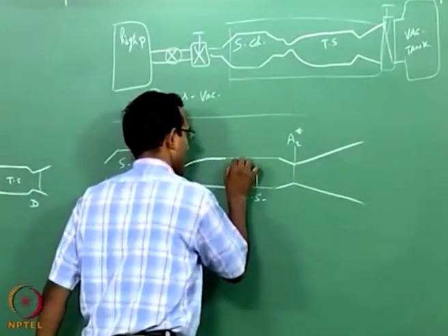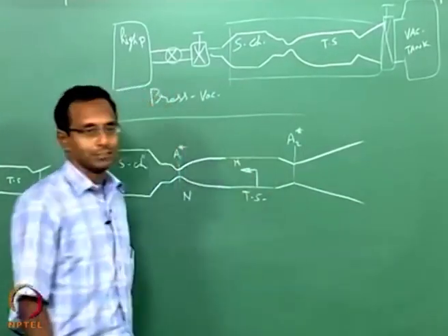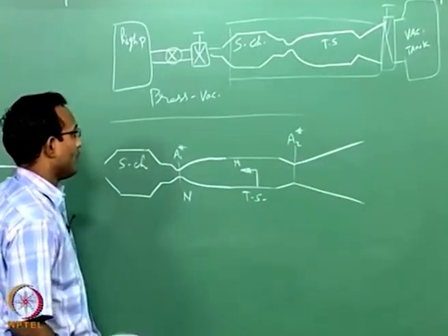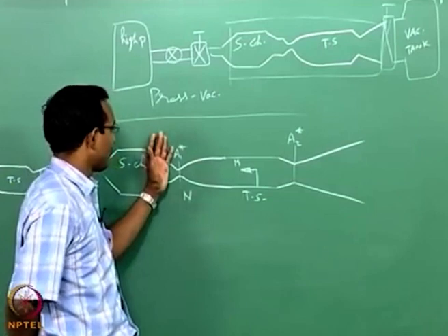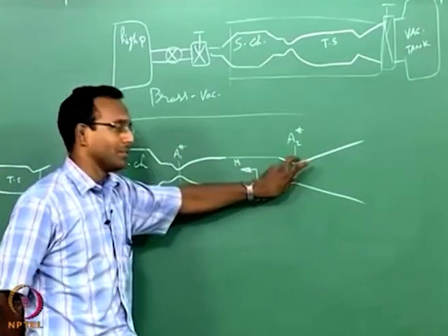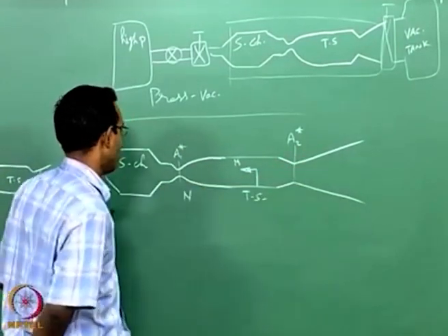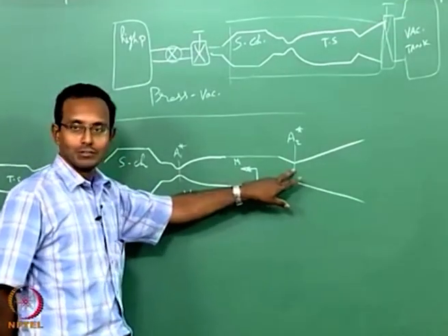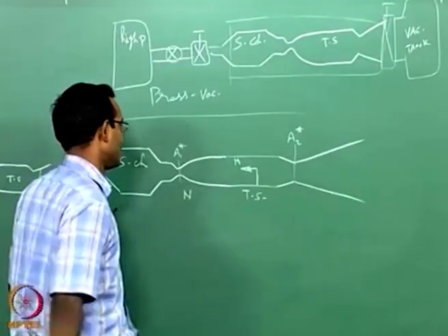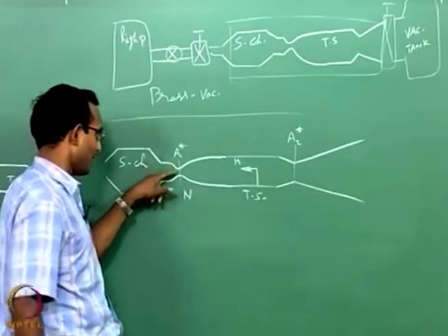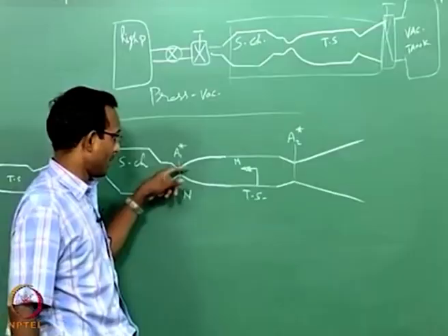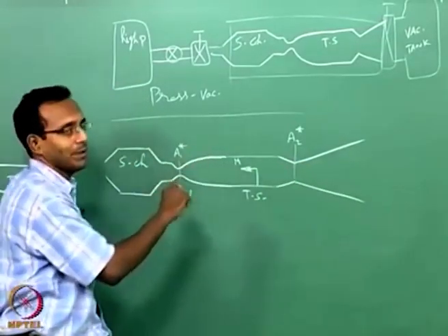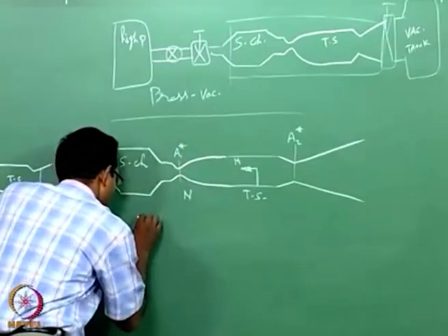And let us say I want some particular Mach number in the test section, M. So, we already discussed the problem of a CD nozzle with another bump in the nozzle, where we said that if I want this not to choke, the mass flow rate coming out through this, which is choked, must be able to go through this one, and we said that the area should be more than a critical value.